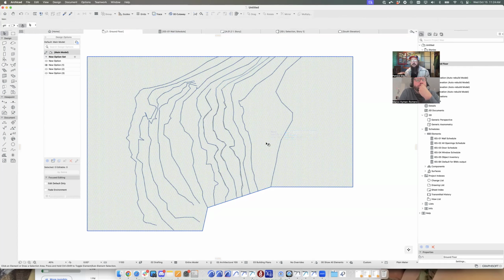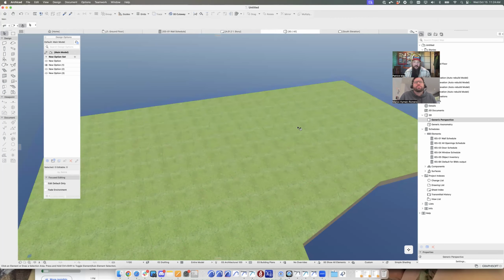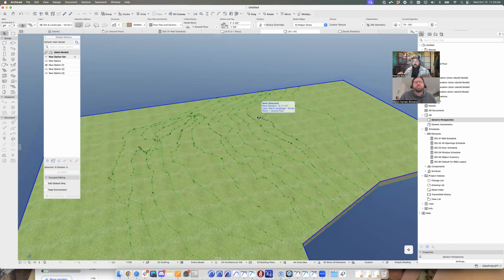This is a lesson learned the hard way, and I'm going to give you this lesson ahead of time. I spent the better part of 6 hours working on a site mesh, pulled it up in 3D, and there was no mesh there. You could select it, hit F4 and Command A, and it would show nodes, contours and edges highlighting, but you couldn't see the thing in 3D because somewhere some contours got twisted around each other.